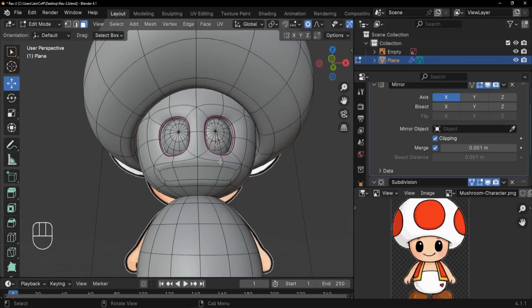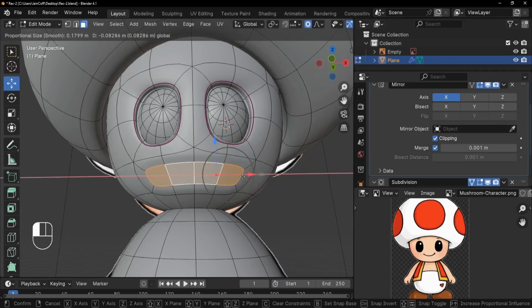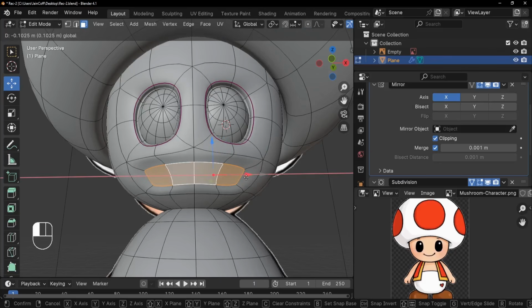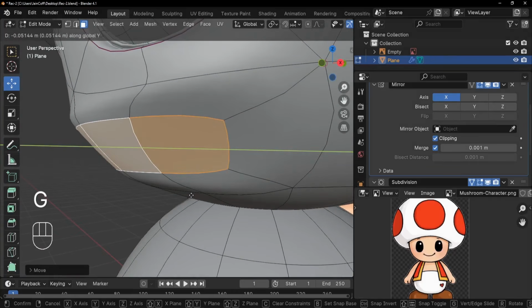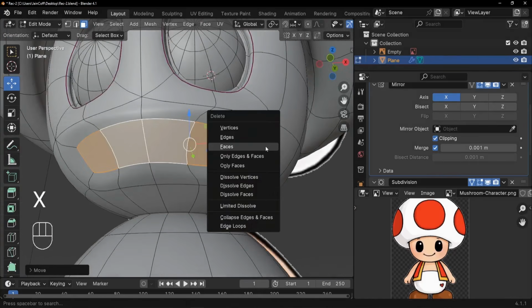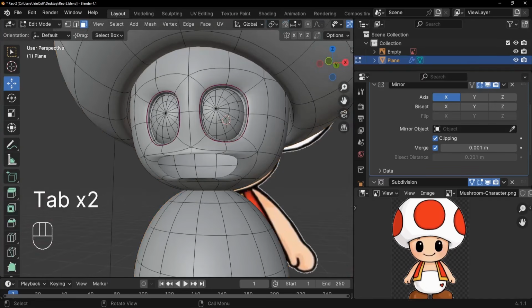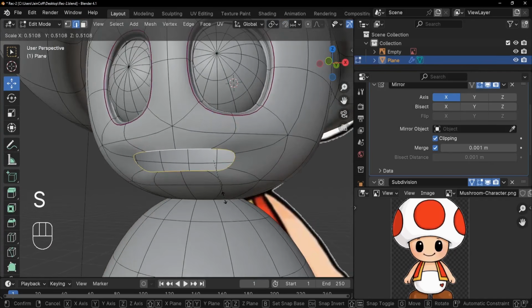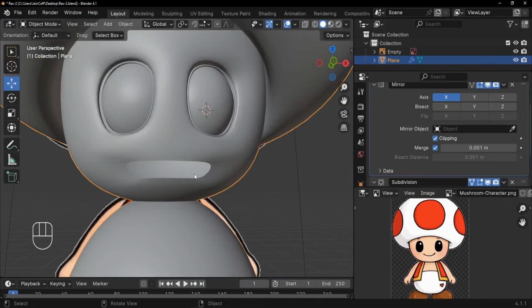All right, after that, I'd like to select these faces. You can drag them a little bit sideways. So here, let's deactivate the proportion editing tool. So something like this, we can try to push it outside, so GY. And we can just delete it. So let's press X and delete that part. Okay, we got a big mouth, so we have to work on it. So let me just try to scale it down. Something like that. All right, so let's give it the right shape.